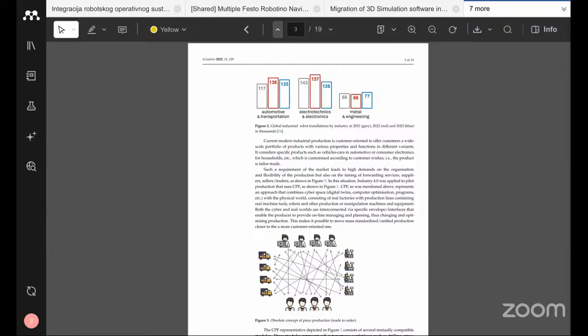What is the duty of the PLC? The duty of PLC is to receive information from the sensor signals, and there is a control program already stored inside the PLC. Based on the control program, the PLC will give the necessary output to the robotic system. Based on that, motors, valves, cylinders, grippers will be controlled. Then the operation status will be sent directly to the central system. Also, this PLC should communicate with the other PLCs in other modules. It will also check the faults and the safety conditions.